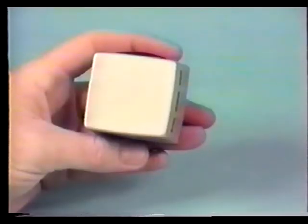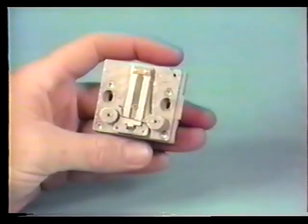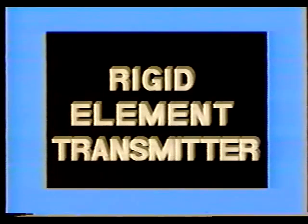There are three basic types of transmitters used in HVAC control systems. They are temperature, humidity, and pressure transmitters. Let's take a look at the various types of temperature transmitters. The first of these is the room or wall transmitter. The room transmitter is designed for wall mounting and, like a pneumatic thermostat, has a decorative cover to conceal the sensing element. Rigid element transmitters are suitable for duct or well mounting.